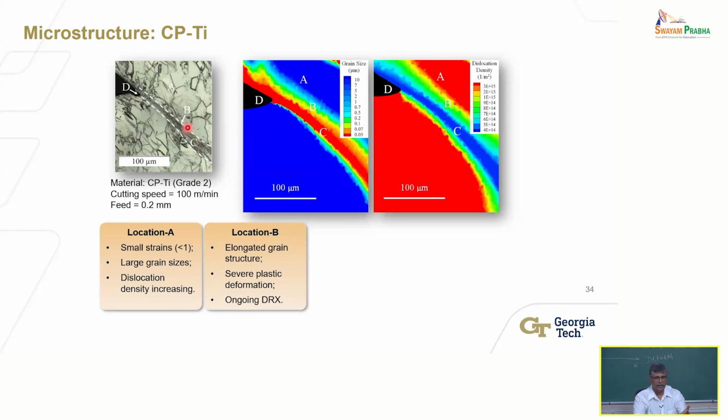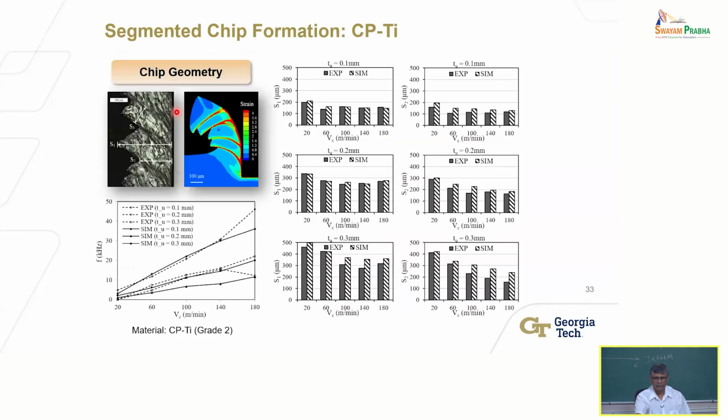You need to go to a much higher magnification tool, such as transmission electron microscopy, for example, or even electron backscatter diffraction, EBSD, okay, which you can do on a SEM. You need to have EBSD capability on that SEM, and it will tell you grains. It may be able to resolve and refine the grain structure in that region. But the surest way would be transmission electron microscopy, actually.